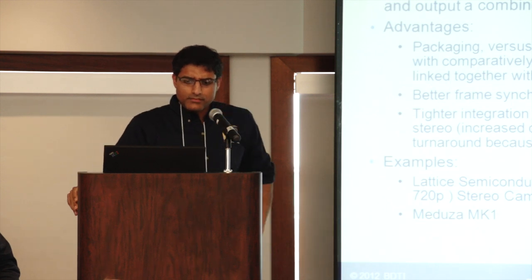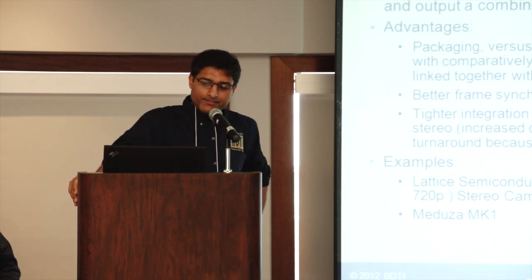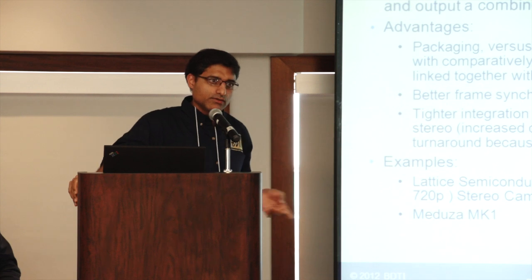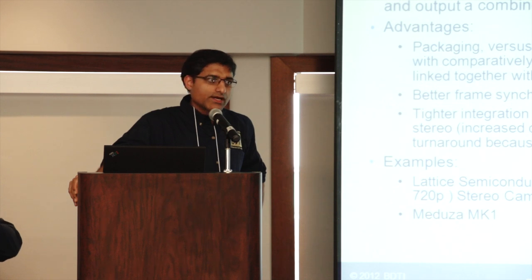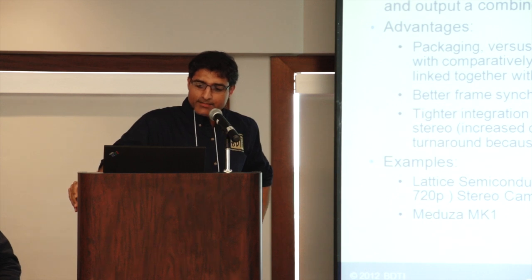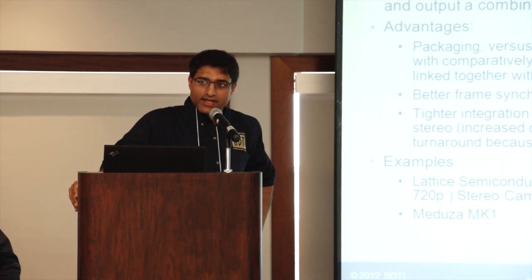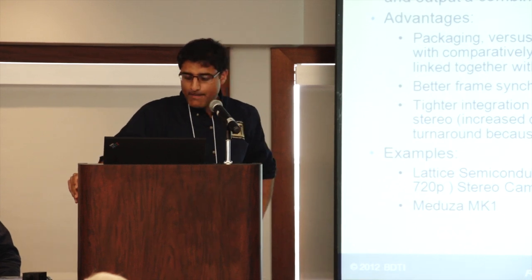Right. So you get better frame synchronization on an integrated system, which means that I can usually accommodate faster motion. And also, the tighter integration leads to better calibration, which in turn leads to better stereo. 2 examples, I don't have pictures of these, but Lattice and Aptina actually announced at CES in January a stereo camera reference design, and then Medusa MK1 is a British company.